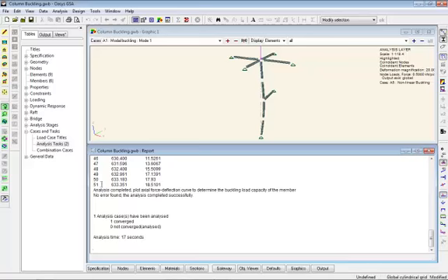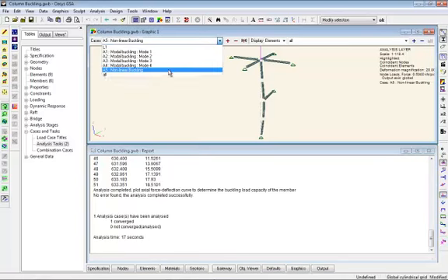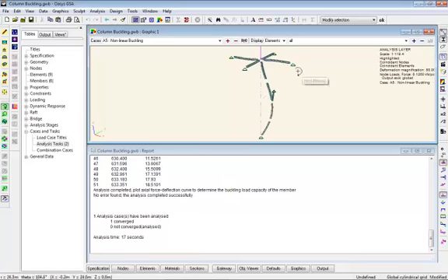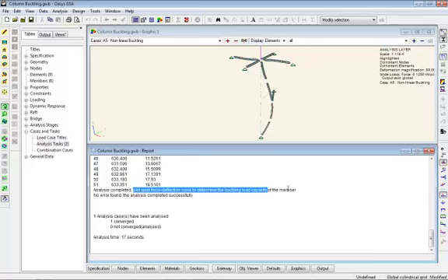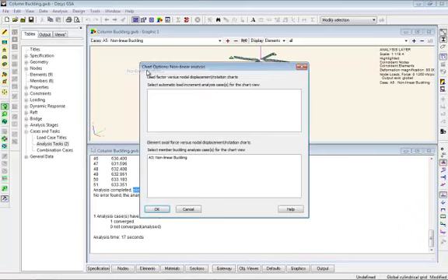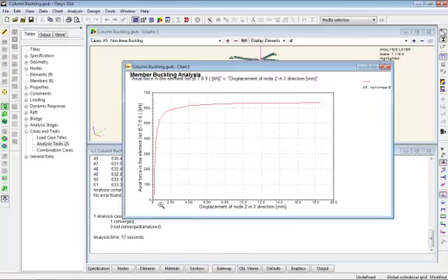And again, see, it's buckled in quite a similar shape to the first modal buckling. But it says to plot the axial force deflection curve to find the capacity. So let's again look under the chart views, nonlinear analysis, nonlinear buckling, and we can see there that as the load increases, deflection gradually increases, and then it reaches the point where the structure basically gives, and we can use this to back calculate a safe working load on this structure.